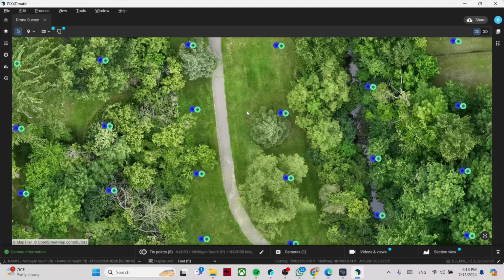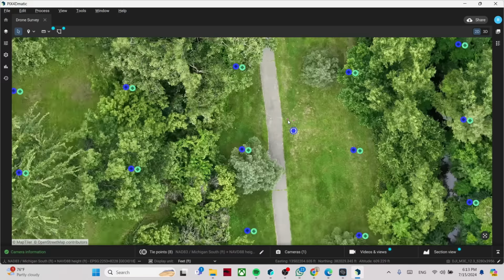That's because if you use a mechanical shutter camera, you're going to get very crisp and clear imagery. And if you've taken hundreds or even thousands of images, when you calibrate those camera positions together and generate a large 3D model, you'll also get a high resolution 2D map. And that's what we call an orthomosaic or an ortho image. So very nice, very clear, very crisp. I love the fact that this came in very nicely.